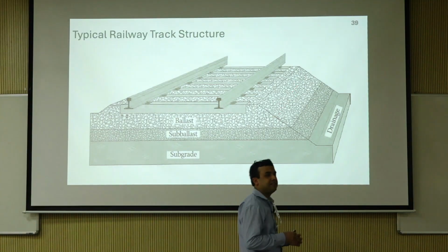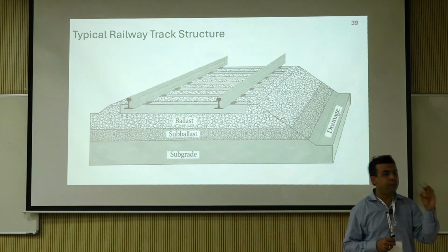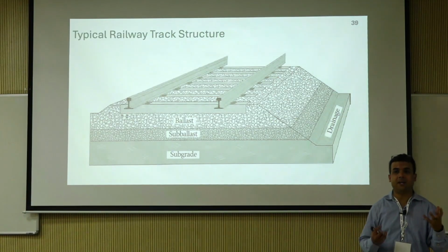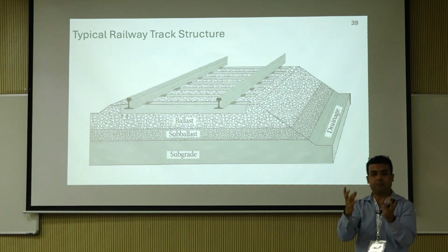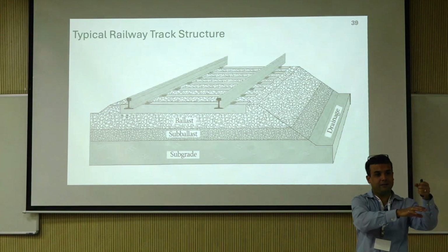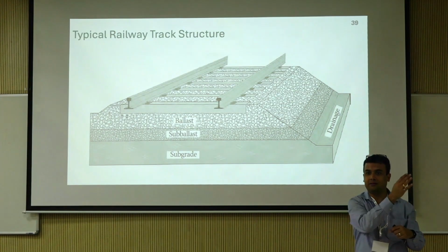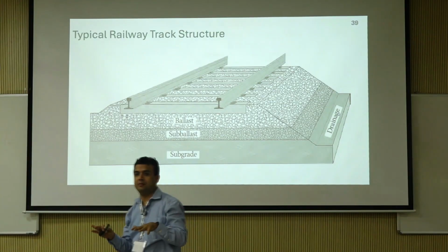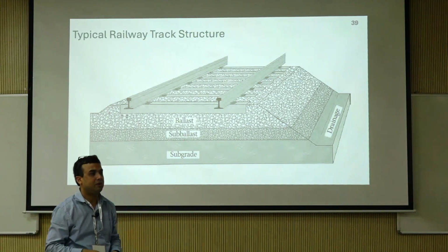One of the biggest challenges is railroad ballast is very, very open graded. And open graded materials are extremely difficult to work with. If you want an example, think of marbles that kids play with. If you put them in a Proctor mold and hammer on this side, the material just rises here. You bump it here, it just rises there. That's what railroad ballast is. It doesn't compact. So you have to vibrate it to the optimum configuration. That's the primary challenge. Otherwise, pretty straightforward stuff.